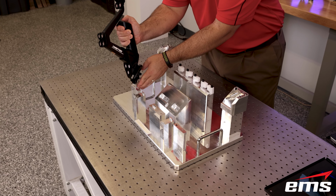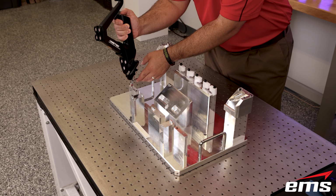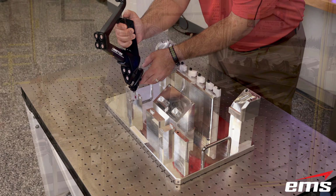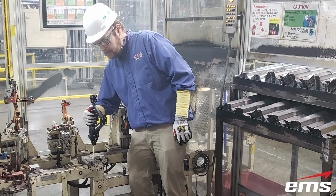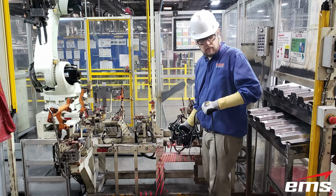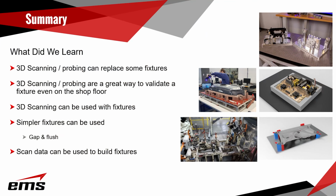Now, 3D scanning and probing is also a great way to validate a fixture, even out on the shop floor. Traditionally, you couldn't take a CMM out on the shop floor, and if you have a very large part, there's just no good way to validate that fixture. Now, as we showed in the example of the welding fixture, we can go right out on the shop floor, establish that datum or Cartesian coordinate system, and fully inspect that fixture, making any adjustments that are necessary, and also checking it from time to time to make sure it's still good.